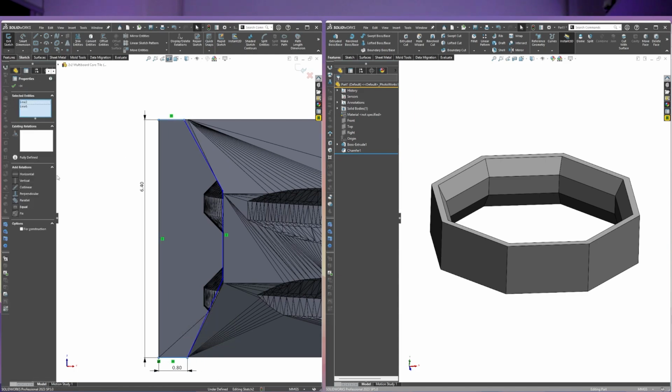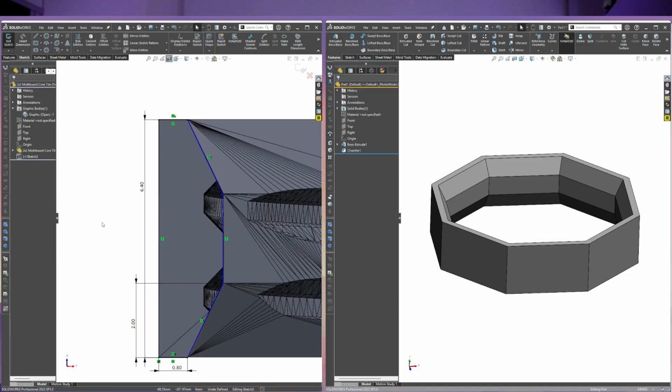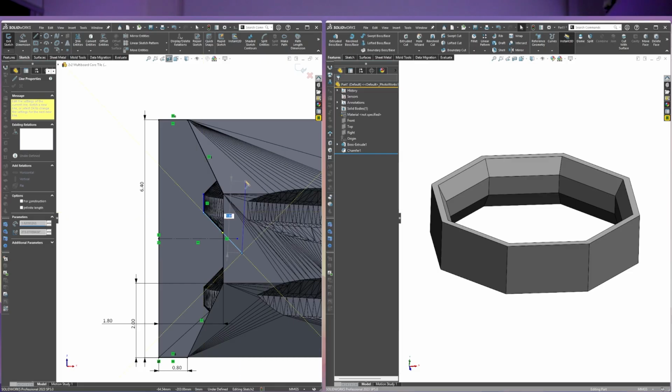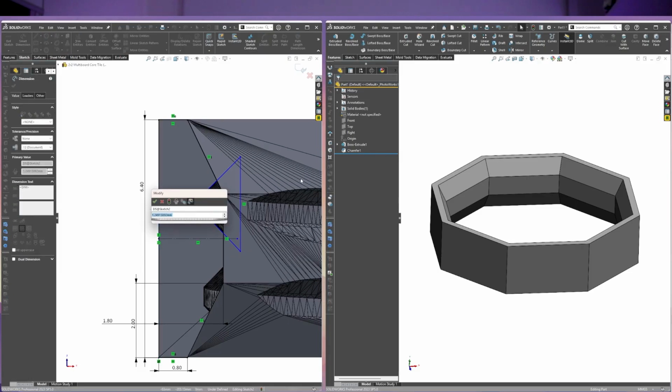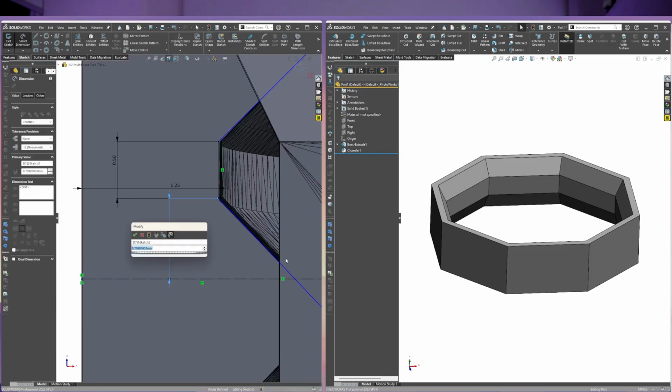All right. So the way I went about that is to create sketch geometry in the reference file, then dimension that geometry, because I'm going to assume that Jonathan, when he's built these files in whatever software he's used for the originals, he's not just making up random numbers for this stuff. It would be controlled. So in a lot of cases, it's going to be round numbers.